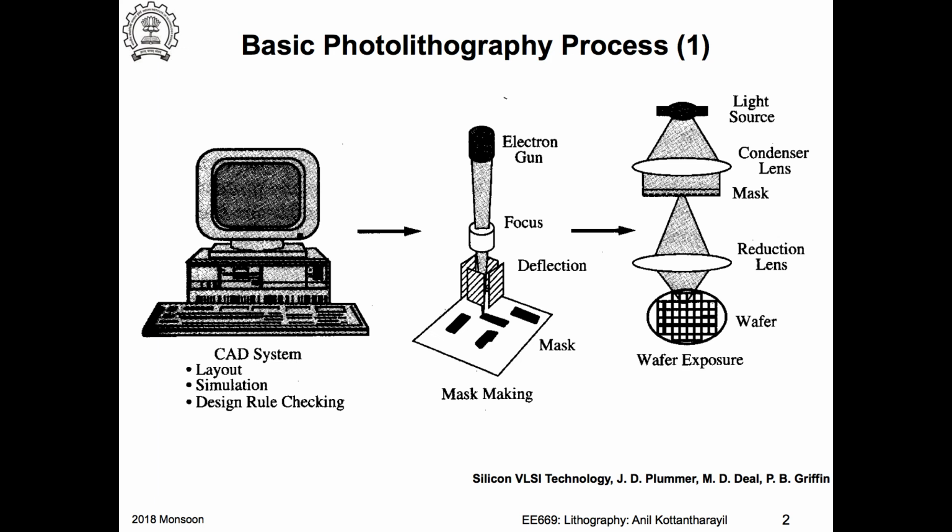So you can get fairly good uniformity, or uniform thickness, of this resist on the wafer, and then you bake it at temperatures around 100 degrees centigrade. Bake means you are getting rid of some of the solvents in the photoresist, so it does not flow any further. Otherwise, if it's a highly viscous fluid and I hold it like this, it will slowly drip down. So I do a baking, so it becomes a solid mass on the wafer surface.